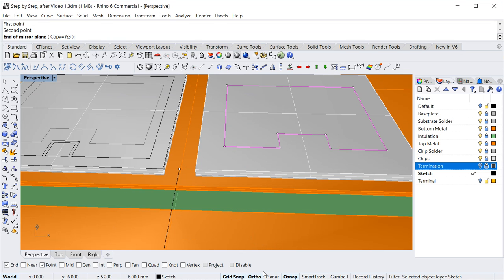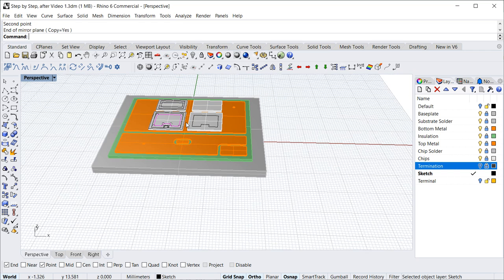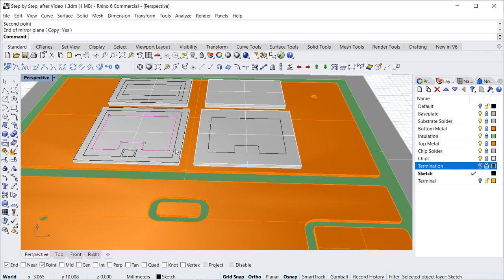So default is that this mode is turned off, and then you can have arbitrary directions, and you have to press the shift key. But I recommend to turn this mode on, then the default is orthogonal direction, and if you want to do something else, then you have to press the shift key. So without shift key, it's always orthogonal. Okay, like this I've mirrored this curve.